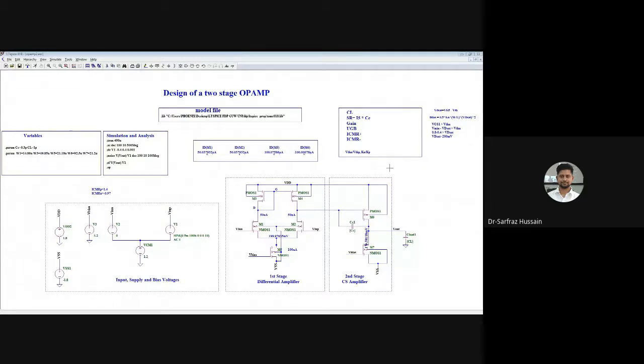So these are the things in this one. Or you can also calculate it like this, like you can put some lower value, but the VDsat value will always be constant because of this bias current. Okay, so now once you have fixed this particular portion of the design, now we can go for the designing of the M1 and M2 transistors.